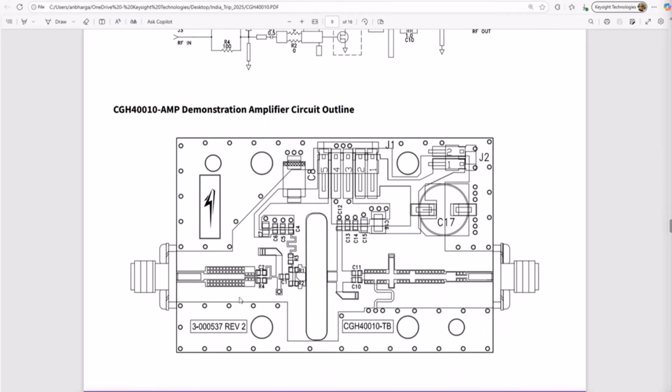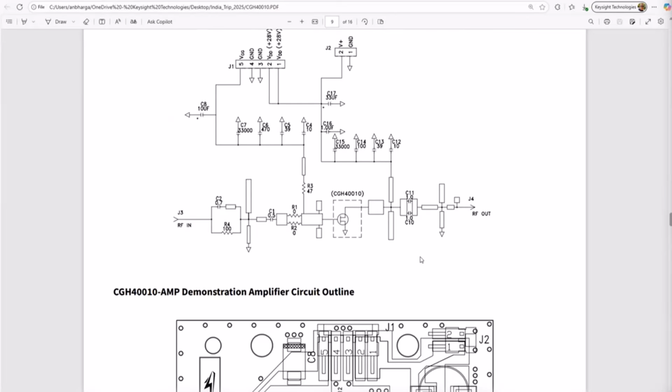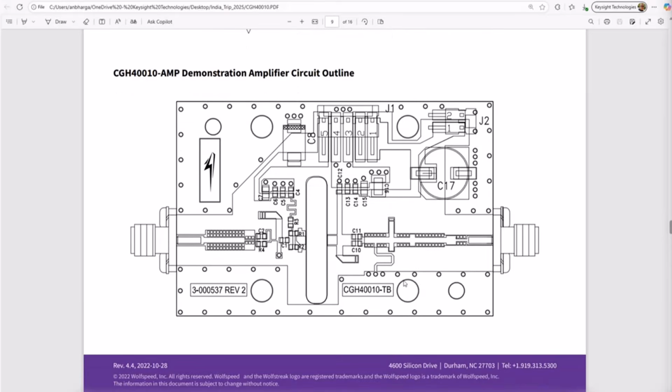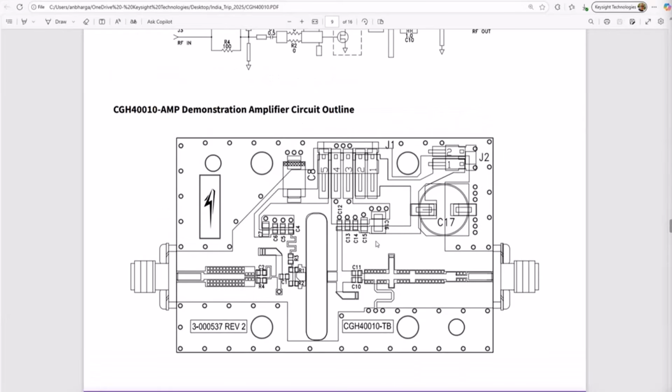So that kind of gives you a good guideline on how you should foresee. Now, based on your design application, your layout may look exactly opposite of what you are seeing here, but at least you get an idea. Another interesting thing, which you will also see in my design, is usually in RF microwave, we avoid putting short circuit stubs. But this device is such that you cannot do a good output impedance matching if you don't do a short circuit stub, right?